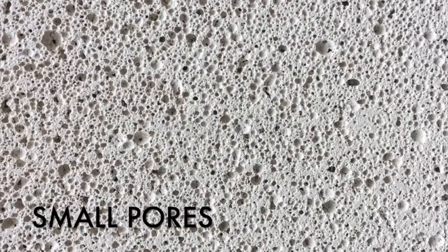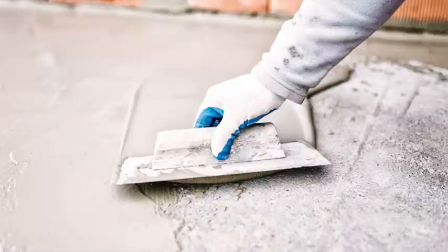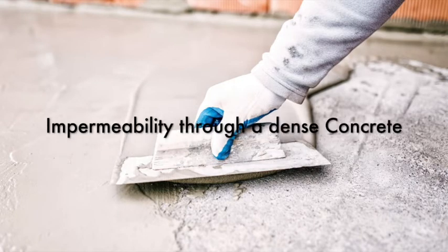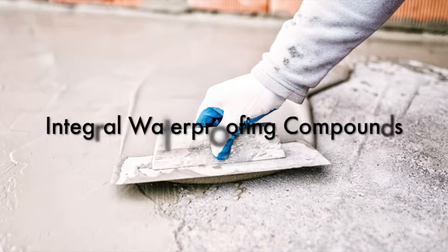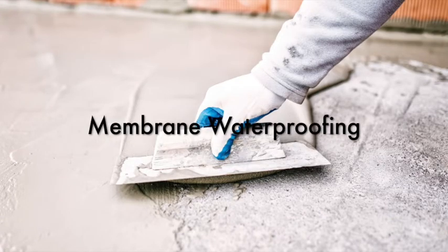If the pores or voids are very minute but connect with one another, theoretically they may act as capillary tubes. But capillary tubes will tend to hold the water and prevent the passage of water. So there are various methods of waterproofing concrete. The first is impermeability through a dense concrete. Second is the waterproofing coating and washes. Third is the integral waterproofing compounds. Fourth is the membrane waterproofing.